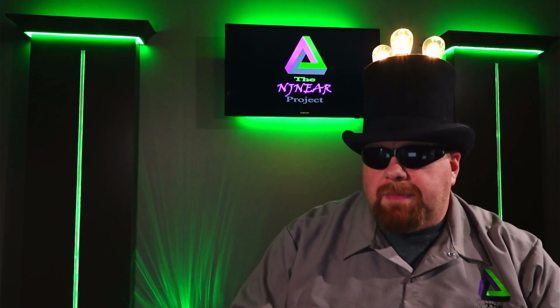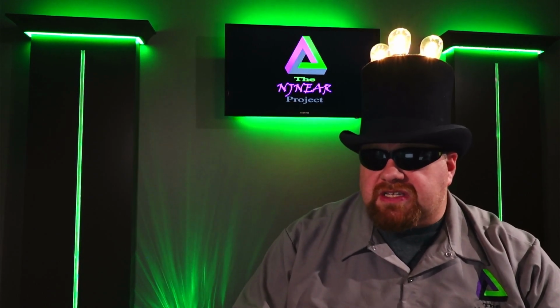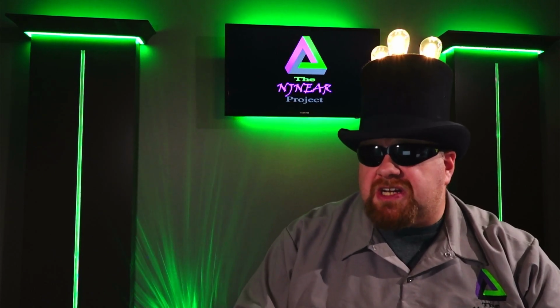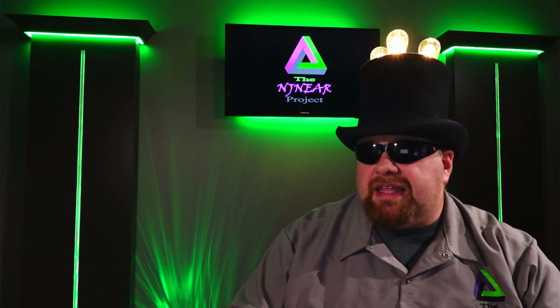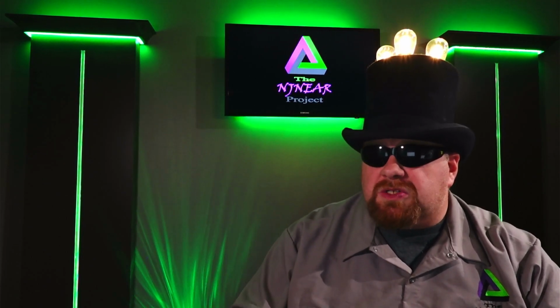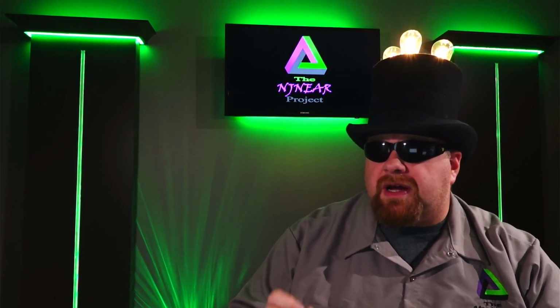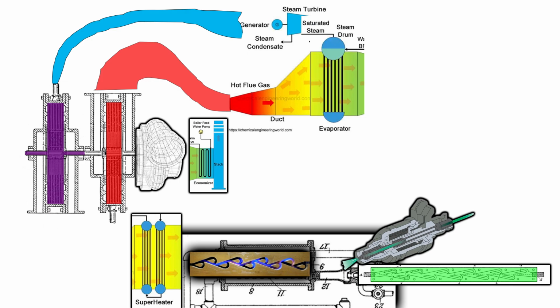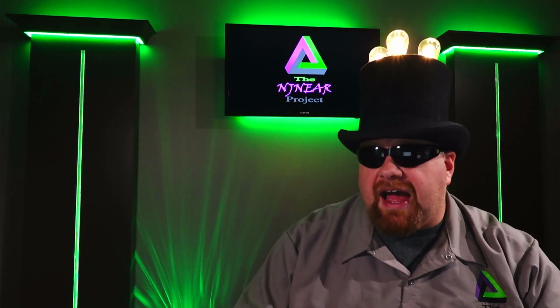Now, something people don't really think about with automotive engines is that they are already boilers. The coolant system is a boiler, but its function is to maintain the engine temperature and keep the fluid from boiling using the radiator. The cooling system on vehicles is basically a preheater or an economizer, so a possible design element we can include is a cooling system for the turbine that would replace the economizer in the heat recovery steam generator. This would allow exhaust from the internal combustion engine to only have to do work on the evaporator in the boiler, which I believe would lead to the highest efficiency.